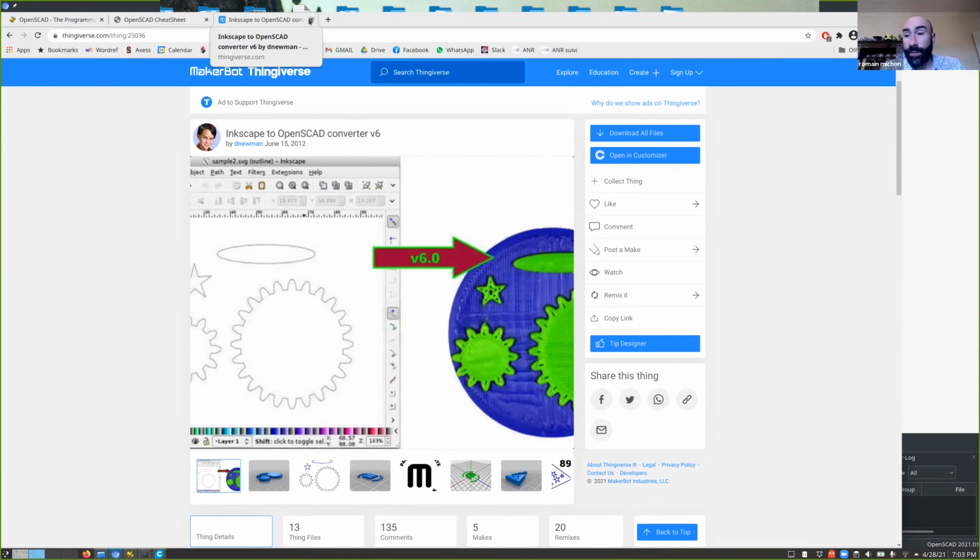So that's for Inkscape. But if you wanted to use DXF or stuff like that, which usually is more 2D, I'm not sure if you can import DXF directly to OpenScad, but DXF is a very basic and open format, so I'm pretty sure that it would be very easy to write a script in MATLAB, as you were mentioning, to generate an OpenScad polygon from a DXF object, because once again it's just a set of coordinates in a 2D space to create a path.